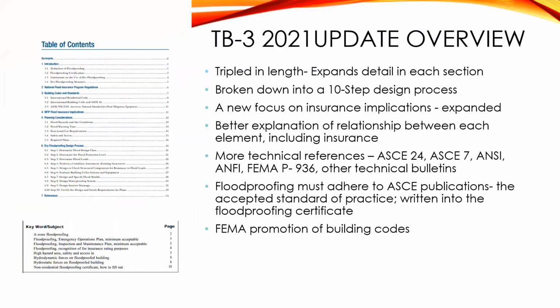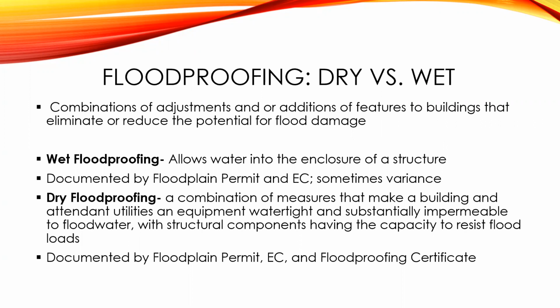Okay, I should probably start with this slide. Just to compare, as we're transitioning from wet floodproofing, which allows water into the enclosure or the compliant structure to allow the pressure to equalize, dry floodproofing is basically the opposite of that, where we're making a building and its utilities watertight and substantially impermeable to floodwater.